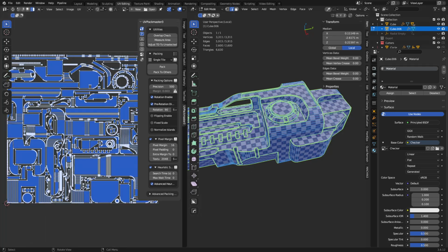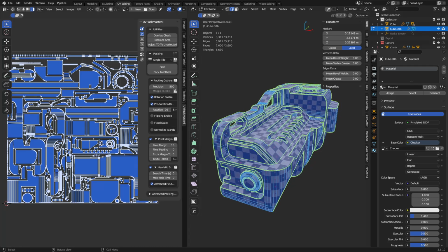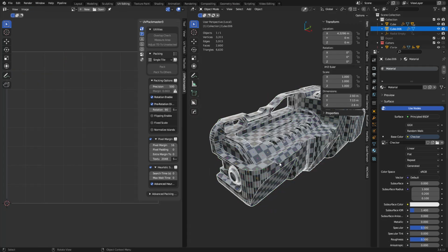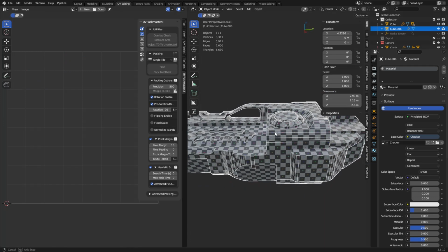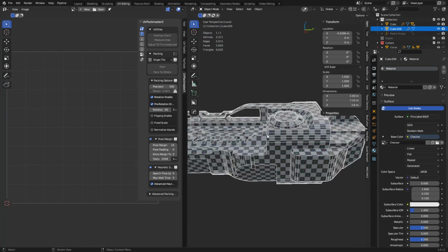And so if that's a problem, usually if you can use any kind of overlapping UVs or breaking it into multiple textures, perhaps texture sets, instead of just using one UV, use 2 UV islands. Anyways, things like that you can do, or material blending as well. There's different techniques to achieve a low poly model. In our case, I think we'd be okay with this. This would probably be like one prop of many, more than likely. So depending on its scale, like if this is something really small, or if this is like the size of a vehicle, we would want to use material layers probably, or trim sheets or seamless textures or something, right?